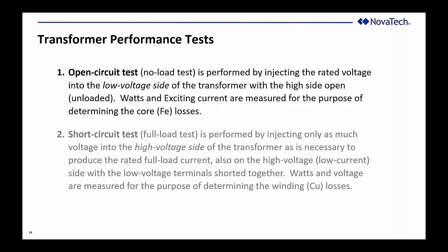The number of turns determines the impedance of the line, and their spacing on the core has something to do with the inductance and the capacitance of adjacent windings. So the manufacturer has a certain loss characteristic in mind when he manufactures the transformer. That's built into the design of the transformer, but once it's done, they have to perform performance tests in order to give you a number that's accurate enough that you can compensate for.